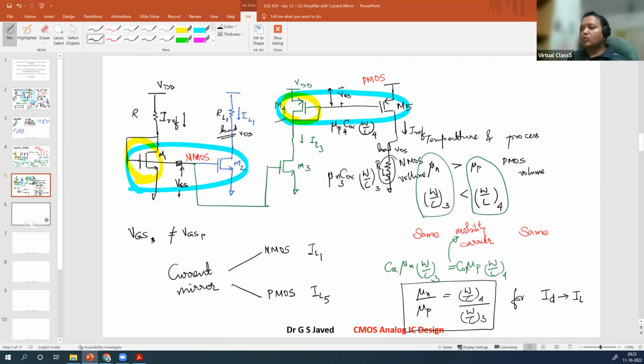So one more, let us look at another angle here. What is this angle? The current flowing to this is a factor of ID, directly dependent upon VGS minus VT the whole square. And the same thing will depend here. This ID will also depend upon VGS minus VT the whole square. Now, intentionally you have to change VGS because the process is changing.